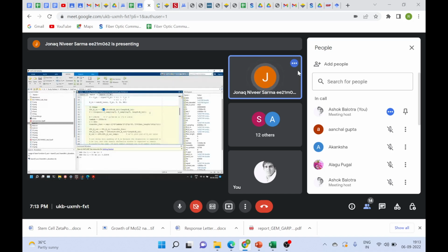It will start with zero frequency first, then the high negative frequencies will start later. Those kinds of intricacies we are avoiding using these two lines. Taking FFT, then FFT shift. Like taking FFT of the input signal, then doing FFT shift.